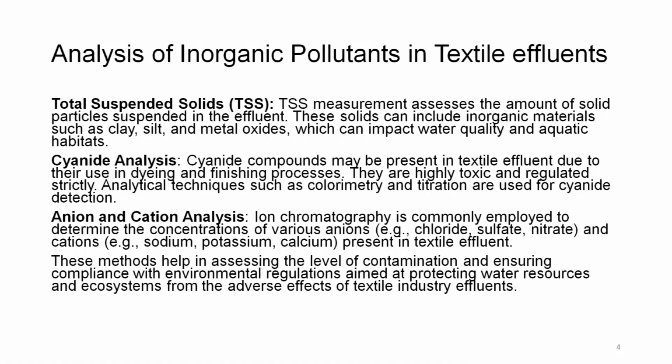Moving on, total suspended solids, TSS. The TSS can be assessed by measuring the amount of solid particles suspended in the effluent. These solids can include inorganic materials such as clay, silt and metal oxide, which can impact water quality and aquatic habitats. So, we have covered TSS, but here we are looking from the inorganic pollutant perspective.